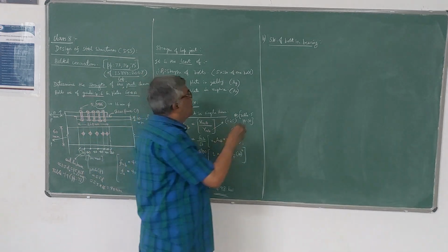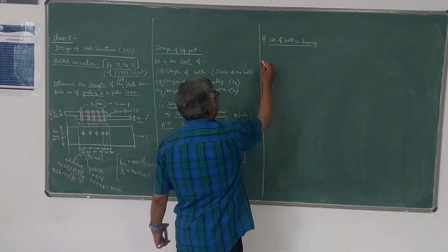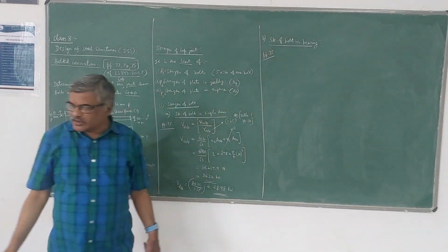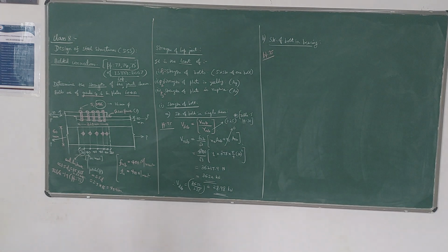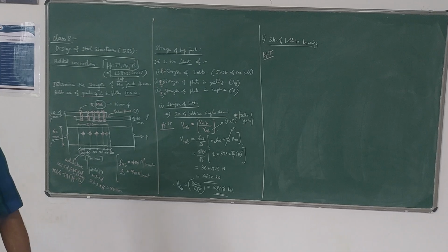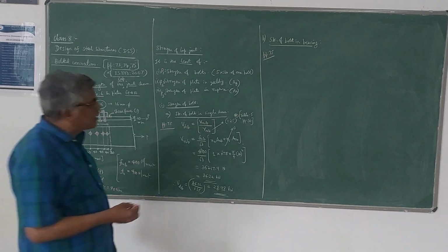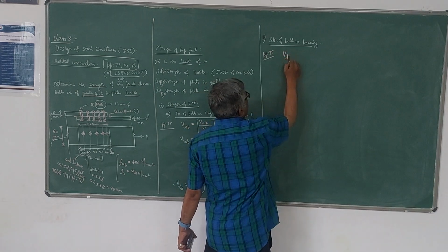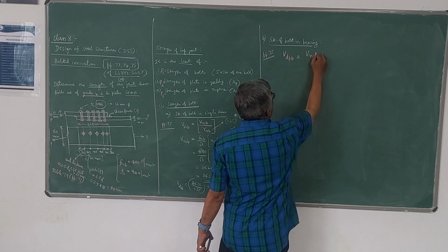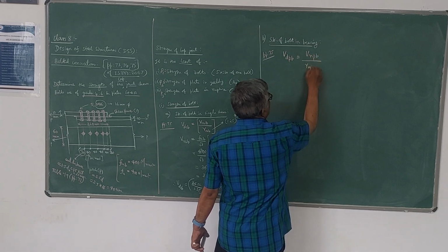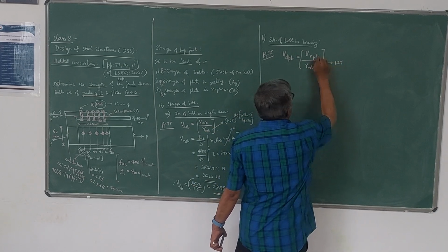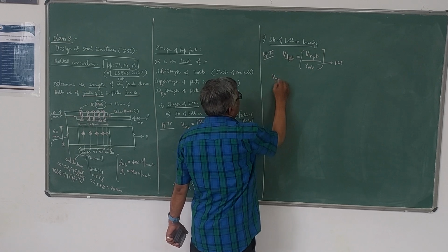Now for this also, you have the formula in page 75. How to calculate the strength of bolt in bearing. The formula is given like this. It is given as VDPB. You can see in that page 75 only. VDPB is equal to VNPB by gamma MB. So you need not remember any formula. It is directly available. So VNPB divided by gamma MB. In this case also gamma MB is 1.25.